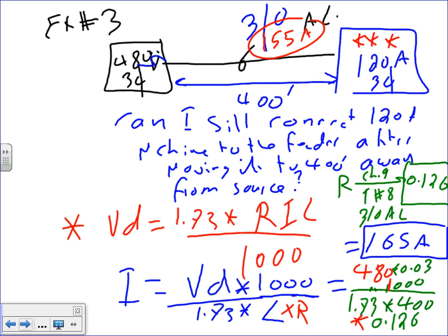Just to give you an idea, let me do that one quick. What's the voltage drop based on this criteria? If you take aluminum, I have copper, I have aluminum here, set mine for aluminum. If I take the voltage for 480 volt, and the current, what was the current? 120 amp, and the distance is 400 length. My voltage drop, the percentage,